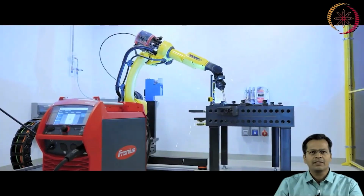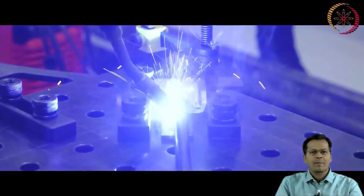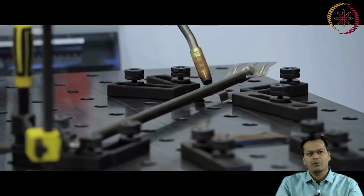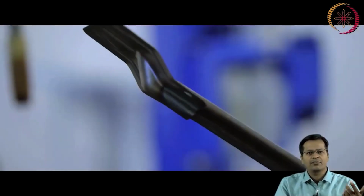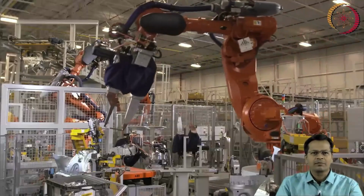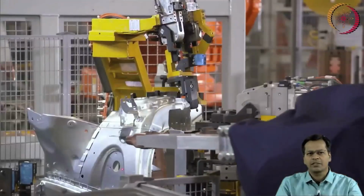Here is one of the very commonly used industrial robots, known as the arc welding robot. This is one of the most demanding tasks in the industry, and robots are applied to do this operation very often. The one you are seeing here is an arc welding operation. Here the robot end effector is mounted with a MIG welding tool, where the wire is fed automatically at a constant rate. You see such a nice outcome. The welding path is taught manually and can be controlled automatically using sensor inputs and a predefined geometry.